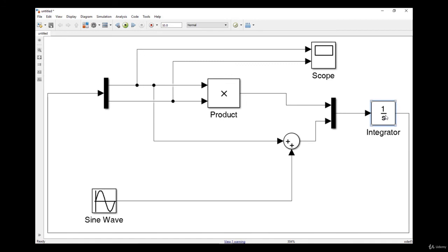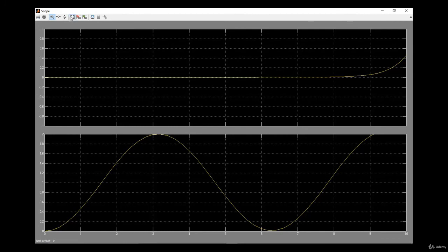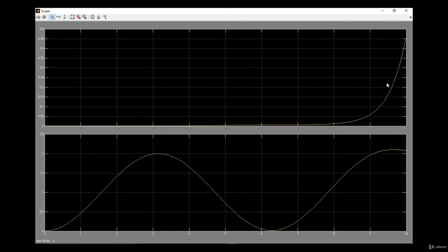The other may be related to the amounts. For example, you give an amount to a specific block and you specify that number with A. Then after running the simulation, you may face an error because A is an unknown amount. I will try to talk about errors later, but generally Simulink itself explains why you have these errors. I change the initial condition, I run the simulation. As you see, because I set the initial condition for my system, the x1 of our system goes to instability.